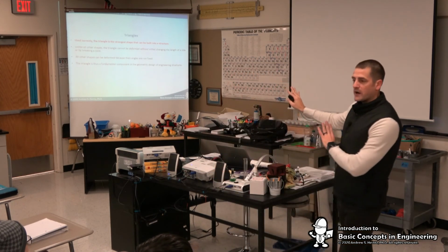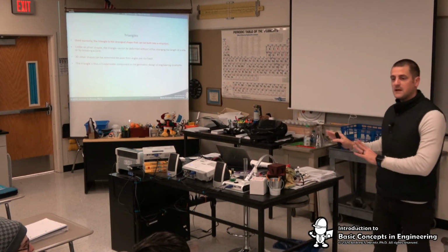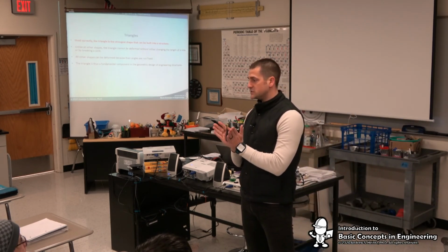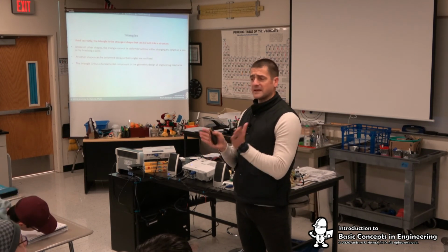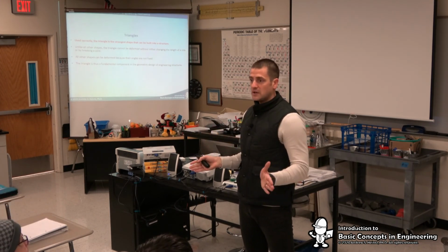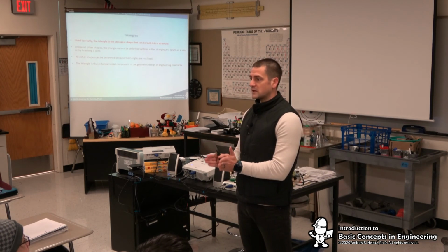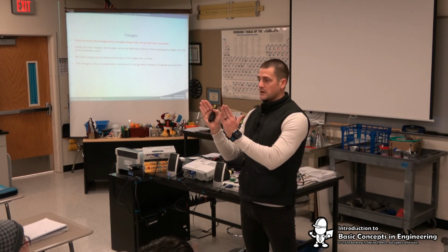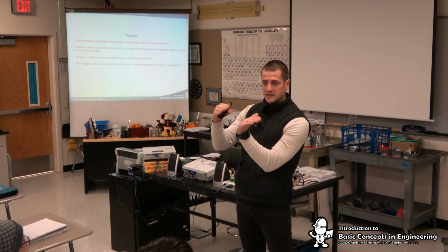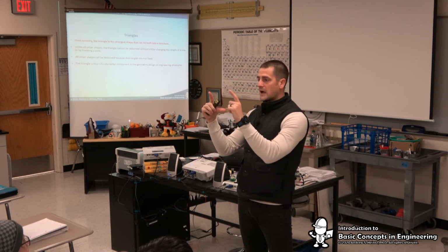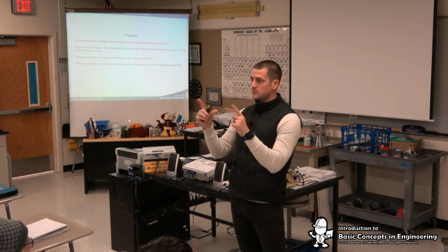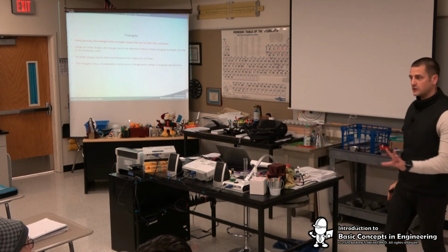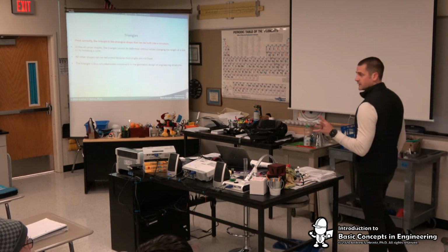So that's functionally why your triangle is your strongest shape, is because the triangle functionally becomes just as strong as any individual member, right? So if you make it out of steel, make it out of toothpicks, make it out of whatever, you have to break the member in order to break the shape. It's the only shape that works like that, right? Like we already saw with the square could maintain all the members the same and it can still tip over. Any parallelogram or whatever you want to come up with, the same. It can move without actually changing the member. So by using the triangle, it becomes just as strong as the material that's used to build this triangle, okay?